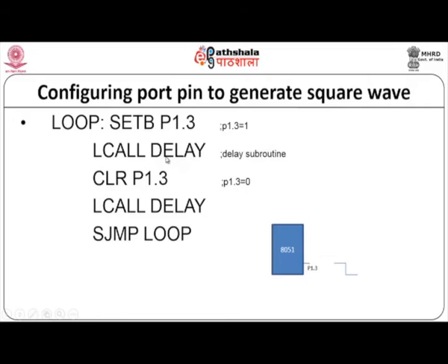This delay is a routine. LCALL is telling you that it is a subroutine long call, that means this delay subroutine is written somewhere far away. So, I will call it with long call and go to that particular subroutine, run that subroutine, and come back. There I am not processing anything, but instead I put in some delay statements, a loop. So, I am not doing any work.